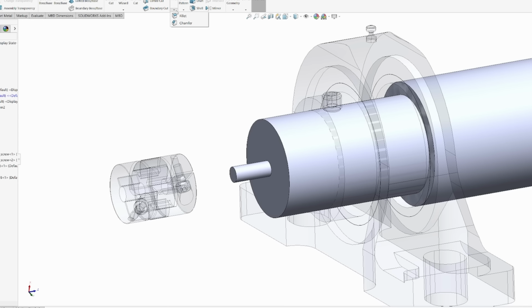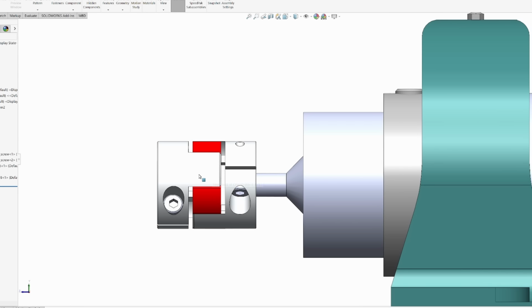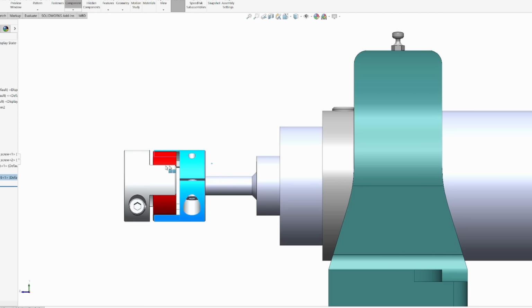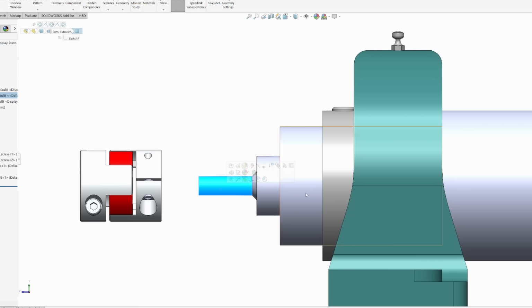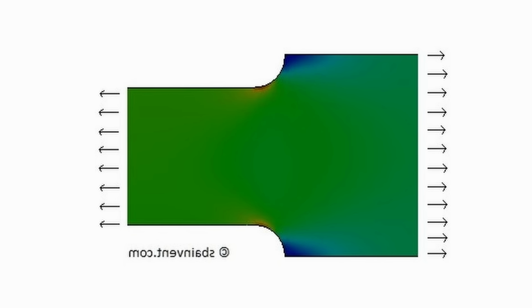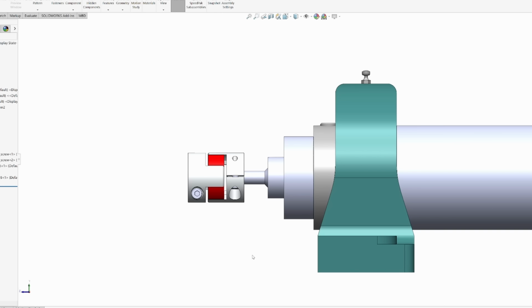So a better approach is to add a proper fillet or chamfer at the transition. An even better approach is to reduce the diameter in multiple steps. This helps in distributing the stress more gradually and reduces the stress concentration. At the same time, it also makes the manufacturing easier and more controlled.